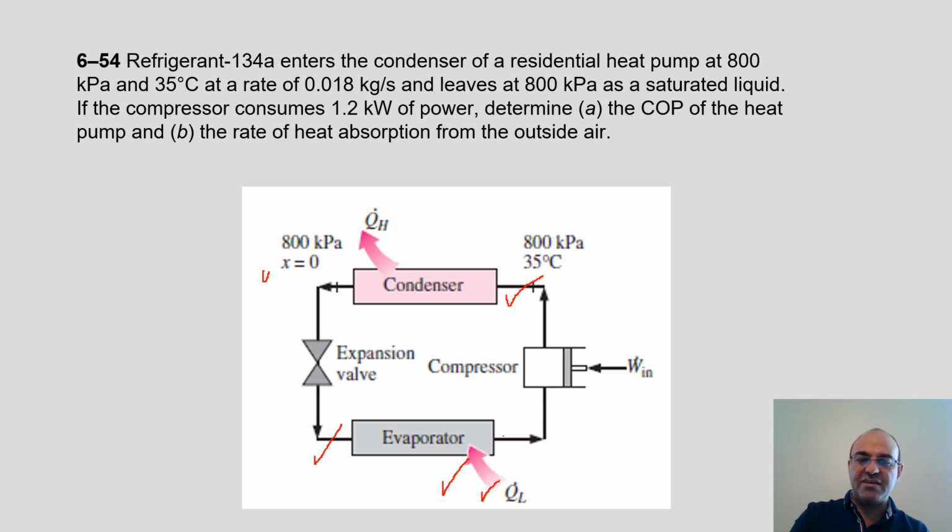At the exit of the evaporator, it is usually in the gaseous form, like saturated refrigerant. Then it enters the compressor. It is compressed, and its pressure increases to a higher level. So now it's ready to undergo another phase change process, but at a higher temperature.